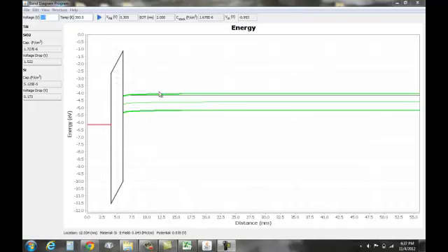As we move over into the silicon, this area of green material is silicon, as I mentioned. And you can see that there is a light line. This line is indicative of the intrinsic energy level. The black line, which is flat, is the Fermi energy of the material. And then you've got the conduction band and valence band.